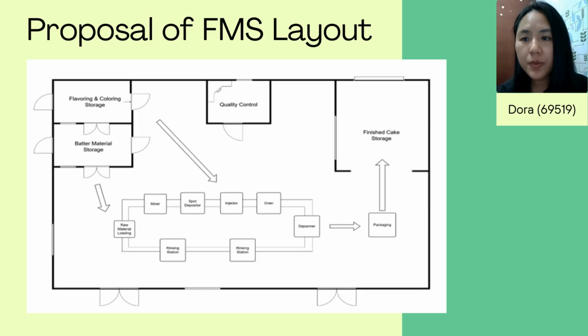We would like to propose an FMS layout to Company Z, where all the parts travel on a conveyor system in a loop. The loading station will consist of both raw material loading and final product retrieval. The process always starts and ends at the opposite end. There are multiple workstations with different machines allocated along the path route. The layout should be constructed in a way that all parts only traverse the loop once to avoid congestion.